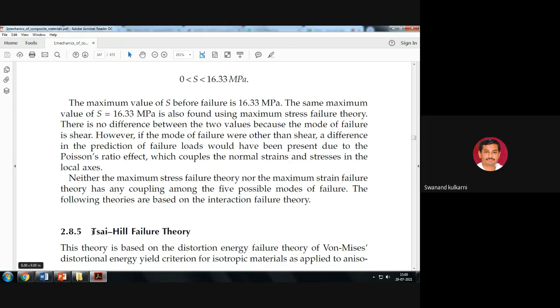Is it okay? So when the von Mises criteria is used, it is based on the energy. When the concept comes with the energy, then that is the von Mises criteria. And when the concept comes with maximum strength, then that is the Saint Venant's criteria. Besides this, whenever the shear concept comes, then it is Tresca. Okay. So let us come to this particular theory, maximum distortion energy theory.